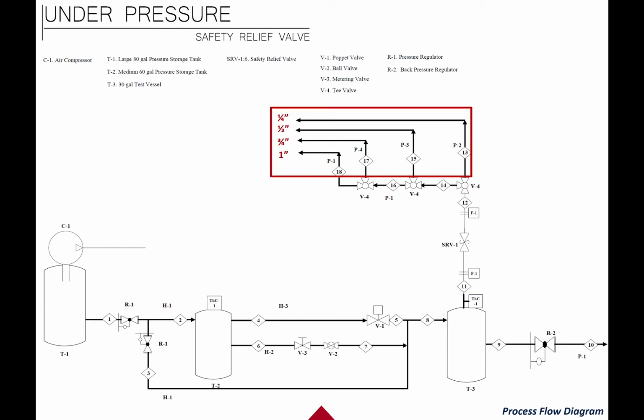The system will cause overpressurization that will cause a safety relief valve chosen by the students to release the excess pressure. 6 safety relief valves will be issued, in which 5 will be resettable and 1 will be non-resettable. Resettable valves have the characteristics of being easy to set and reset, whereas the non-resettable valves require resetting by hand and have a disadvantage of having a one-time use.